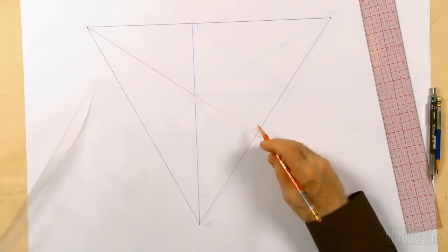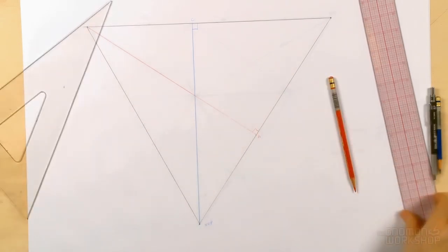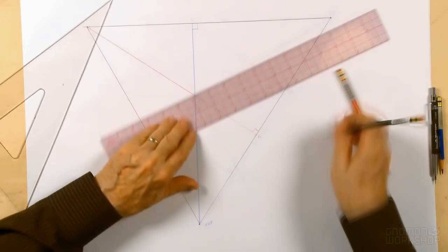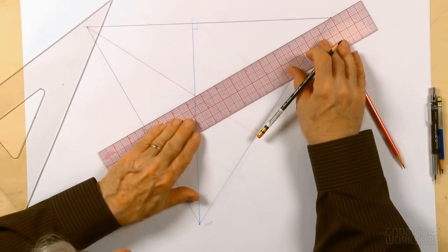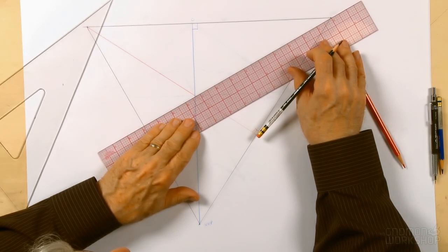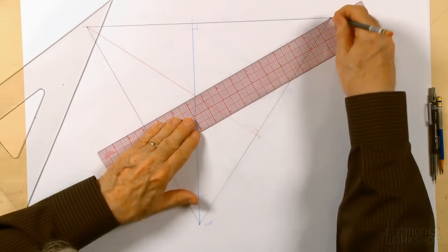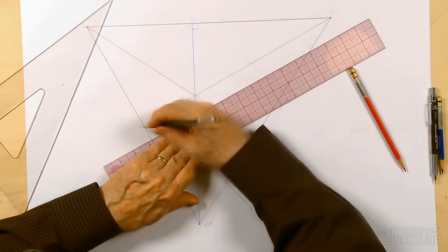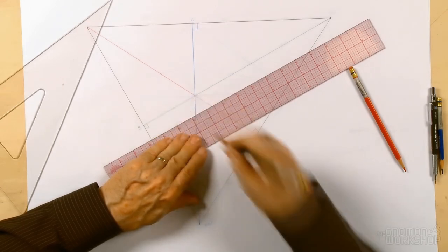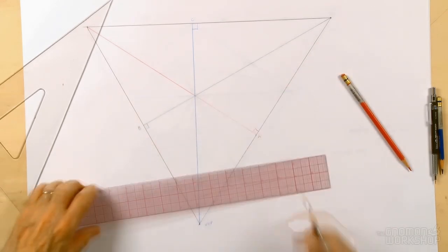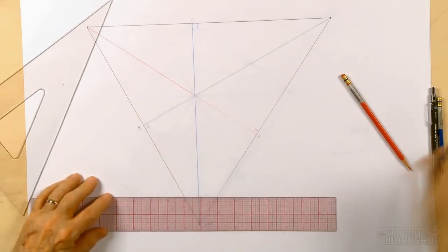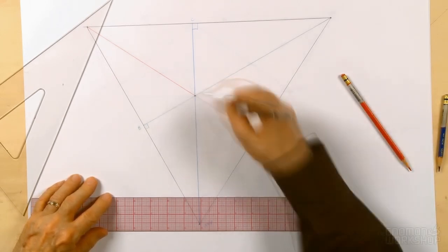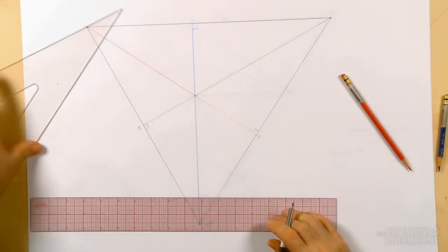All right? Now, automatically, I should be able to then draw the green right reference line coming from the right vanishing point through the center of vision, like this. The center of vision is where all these lines meet in here. I'm going to identify that as point B, by the way. This is a case where the center of vision is not on the horizon line.